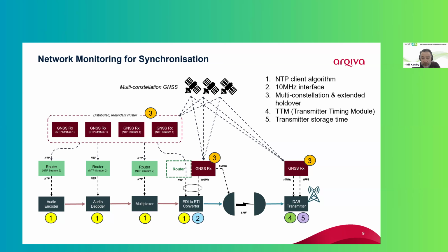And then finally, we also measure constantly transmitter storage times. So storage times will be constantly changing by a small amount because of path variation into the transmitter, but we don't expect large leaps. So we have windows where we make sure that the transmitter doesn't exceed a set value to make sure that the transmitter stays within a certain window of operation.